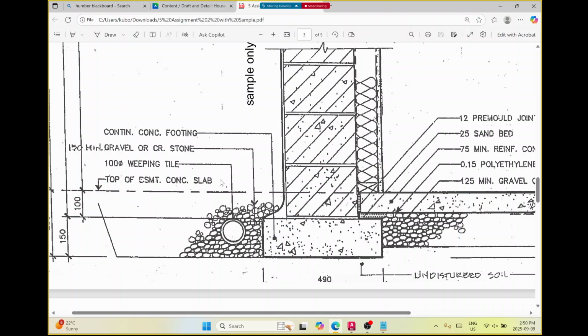They'll also double it up, so they'll label it later on further up in the drawing. They'll probably have an arrow pointing to it that says something like 290 millimeter concrete block, and so on. So it'll tell you what it is. But these notations are quick ways of understanding that. Same with this gravel layer and other things. So we'll worry about hatching it later.